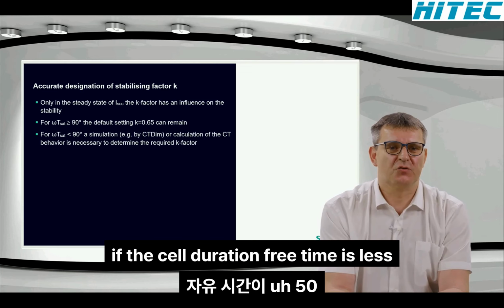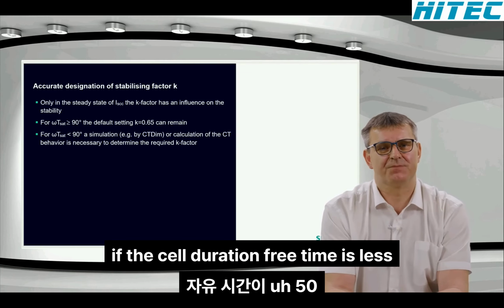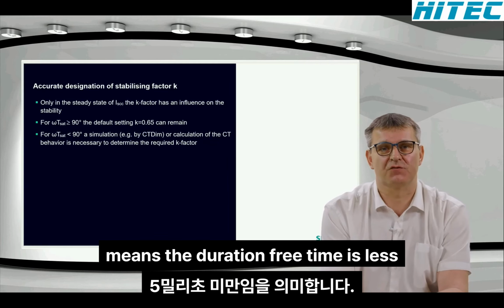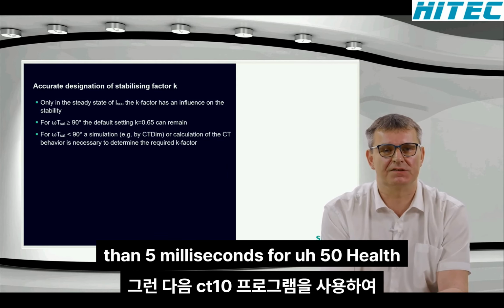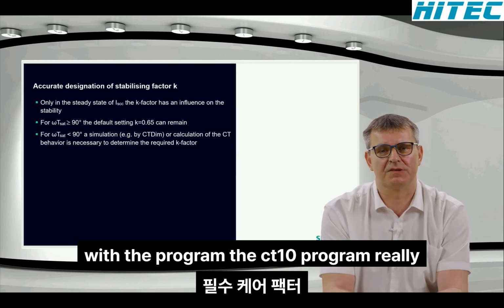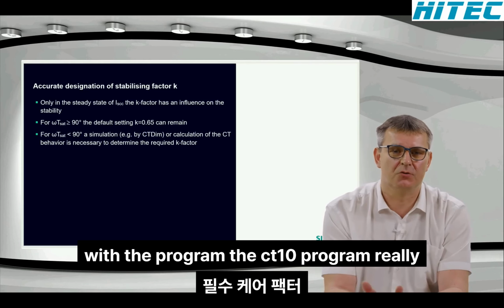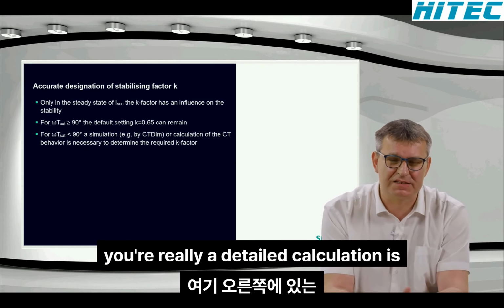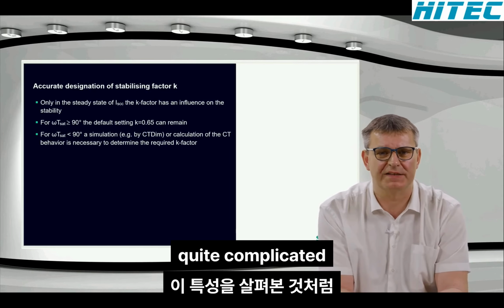If the saturation-free time is less than 90 degrees, meaning the saturation-free time is less than 5 milliseconds for 50 Hertz systems, then we should simulate this with the program, the CT-TIM program, to determine the required K factor. Here a detailed calculation is quite complicated.